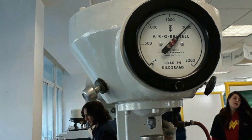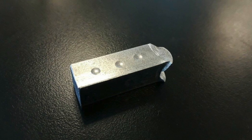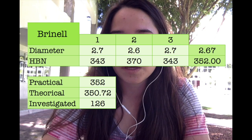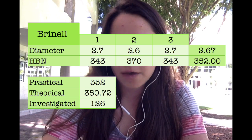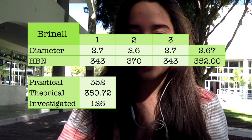For the Brinell hardness test, we applied a load of 2,000 kilograms and we got an average diameter of 2.67 with the 3 indentations and an average hardness of 352, which is the practical one. Then we used this average for the theoretical one and got a result of 350.72, while the investigated one was 126. As we can see, the practical and theoretical values are really similar, but when we compare them with the investigated one, we can see that it's doubling its value.